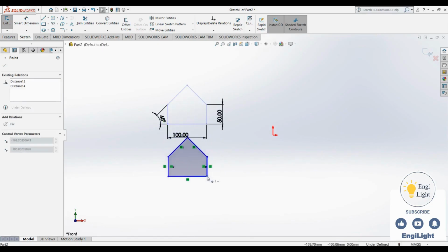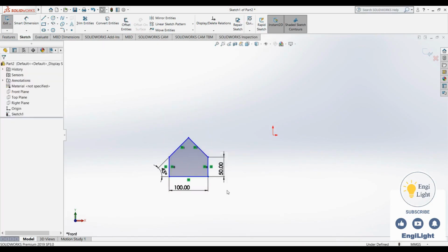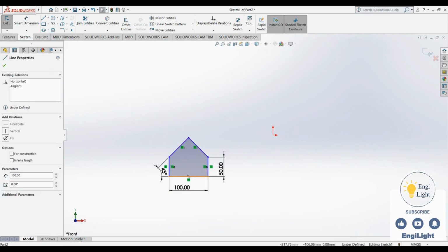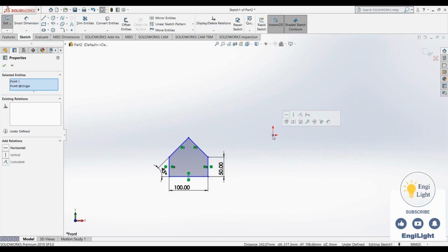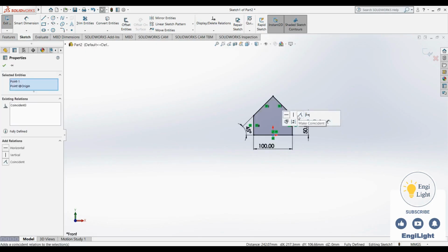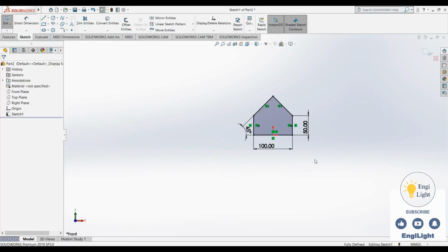This time, we're using a different approach. SolidWorks shows us the midpoints of line segments. When you hover over the line, the yellow point that appears highlights the midpoint of the line segment. Or, for this line segment, this yellow point is at the midpoint. I select this point, hold Ctrl, select this point as well, and then choose the coincident relation. Now, we can see that, much easier, our origin is positioned here, and the sketch is fully defined.